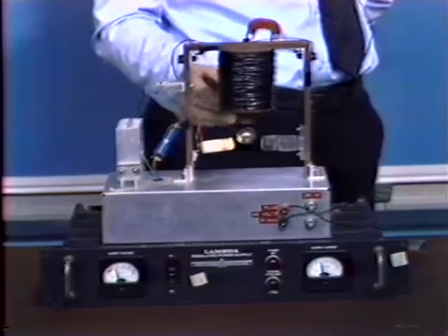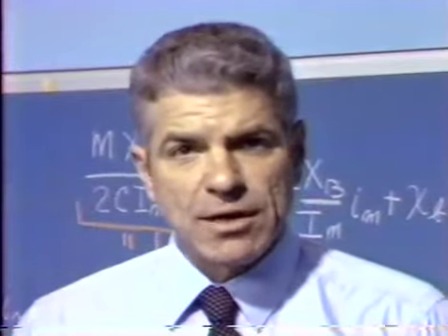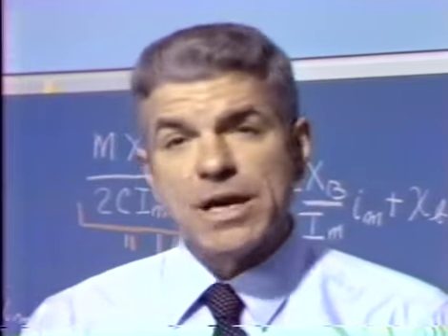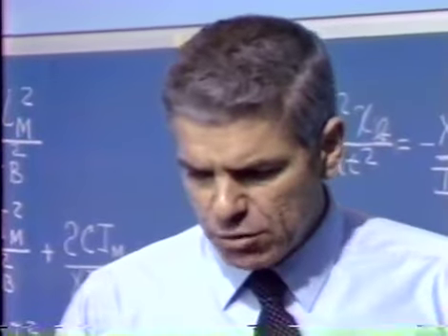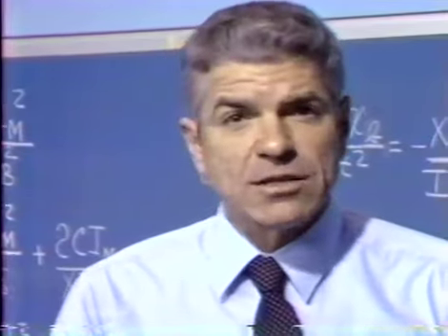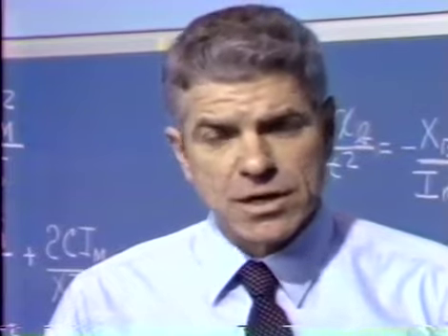You add the permanent magnet field to that associated with the coil, but operating points are chosen so that the magnetic field associated with the coil at the operating point is 0, and all the coil does is basically stabilize the system. And you can put a little subsidiary loop around the thing that with a rather long time constant kind of adjusts operating points to be the operating point where the coil current is 0.